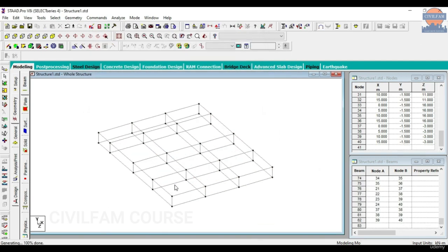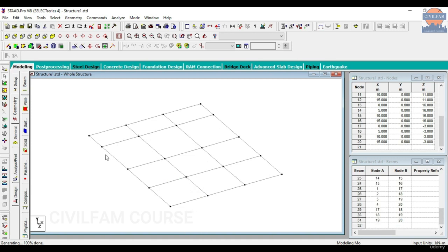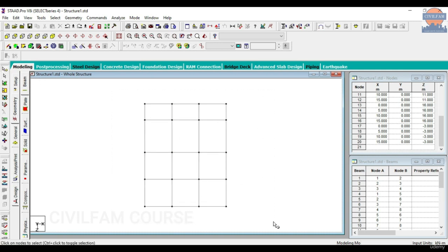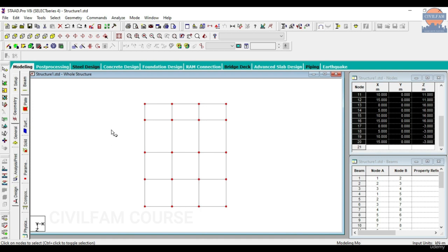But now if you see, I'm getting these beams also, no? In the foundation level we won't have beams, right? This is wrong. So let me use Control Z. Is there any other method that I can use? The answer is yes. Just click on node cursor now. If you don't want these beams to be selected and replicated with you, just select the node cursor, go to the plan view and select the whole thing like this. Then what happens? Only the nodes will get selected.